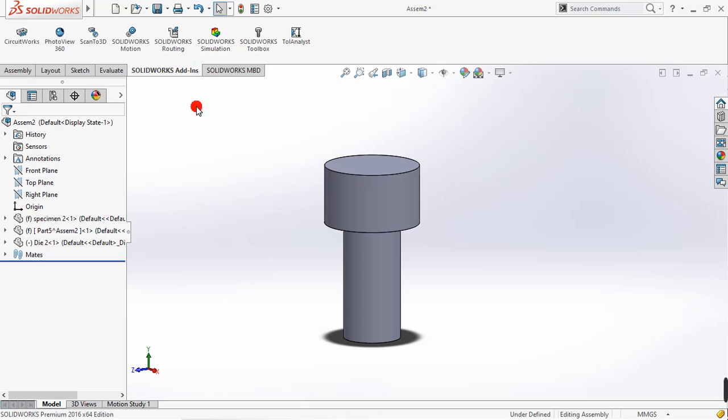The first one is by browsing the SolidWorks add-ins tab. Within this tab, you can find the SolidWorks simulation icon. So you can click this one, and then it will load for some time. So be patient. Okay, so you can determine if the SolidWorks simulation has been activated because the icon will be